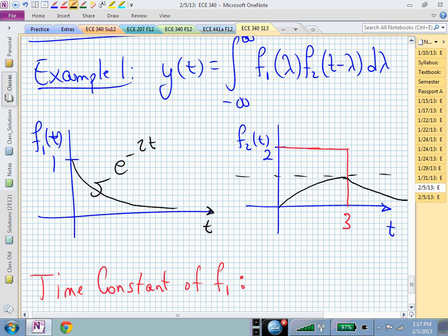So it's effectively flat from 2.5 to 3, correct. And it's probably effectively flat in our sketching accuracy at 4 time constants, so at 2. So it's pretty much flat for an entire second, and then it rolls off, because we're within 2% of our final value after 4 time constants. And by sketching, I can't draw a 2% accuracy with paper and pencil. Let's see. We'll figure that one out. Okay?